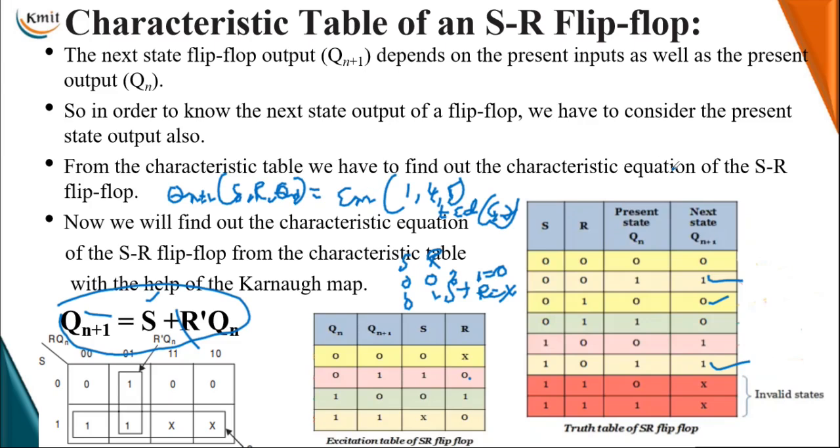In this 1 to 1 transition, the first case is S input 0, R input 0. The second case is S input 1, R input 0. Observing the two cases, R is always 0 and S must be a don't care. Hence the 1 to 1 transition is don't care and 0. These excitation tables are very useful while designing registers or counters. So for every flip-flop, you have to derive the characteristic equation and the excitation table from its state table. So this is the SR flip-flop. Next class, let me learn about the clocked D flip-flop.